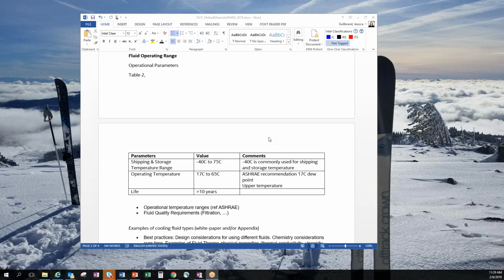Yeah, and these are the discussions that I was really hoping for. How many suppliers do really ship systems charged? I think we don't, but other people do. So the people that do ship them charged are going to want it good to 40 below, and the people that don't are going to want just regular old water, which has better cooling performance than glycol water solutions.